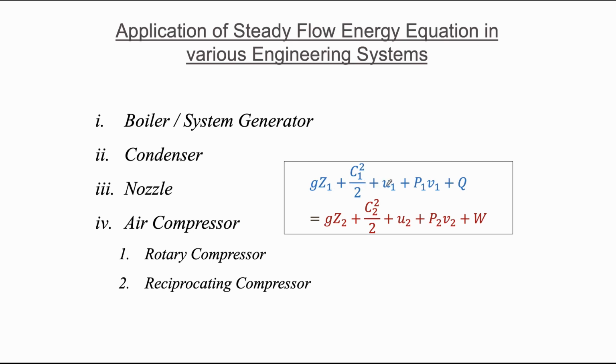plus internal energy plus flow energy plus heat supplied to the system on the left hand side or at the inlet side, which is equal to the outlet side potential energy plus kinetic energy plus internal energy plus flow energy plus the work delivered by the system.